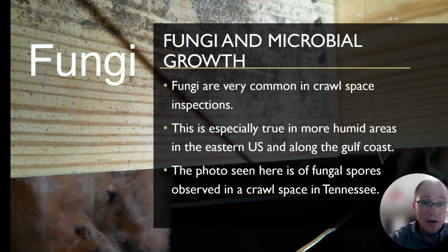In this photo here, these are fungal spores of a crawl space we observed in the state of Tennessee. But I just wanted everybody to know, really look at the floor joists, look at areas that might have fungi like this. You can even take your finger and smear across them and see if those fungal spores smear, then you're definitely going to know they're active, whereas they could be dead if they don't smear. But again, if you're seeing them, it's better to err on the side that they are active and is something you need to look at performing treatment for.